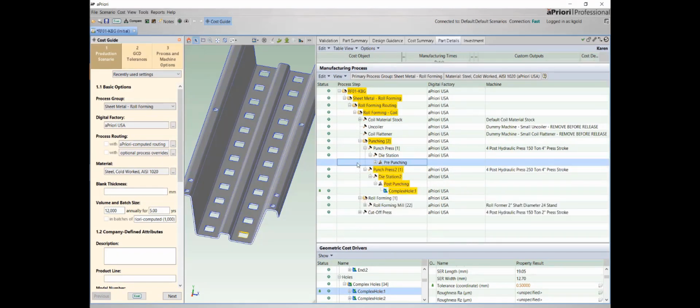One thing I wanted to comment on is that while pre-punching typically is performed using a stationary die with some extra buffer loops of coil material on either side of it, post-punching dies and the cutoff die both are accelerated dies. They need to be accelerated so that they're moving at the line speed when they contact the part. So we calculate which speeds are achievable given the estimated mass of the punching and cutoff dies and the distance that they have to accelerate, which is the length of the part.